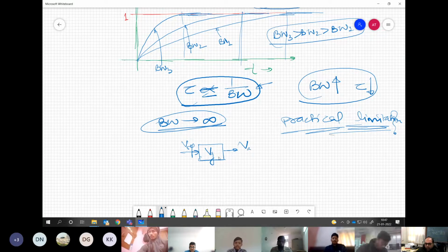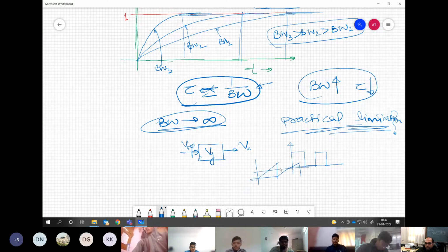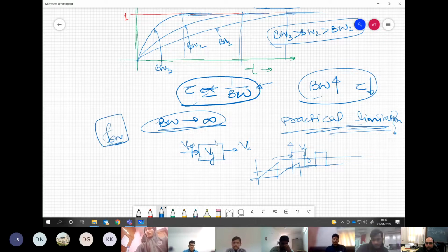So basically the output is generated on account of some PWM operation, right? This Vref is fed to some carrier waveform, and then the comparison generates this output voltage, say Vg, and 0 it will be going, and the average value will be coming out. So we are somewhere bound with the switching frequency and the operation of the converter.